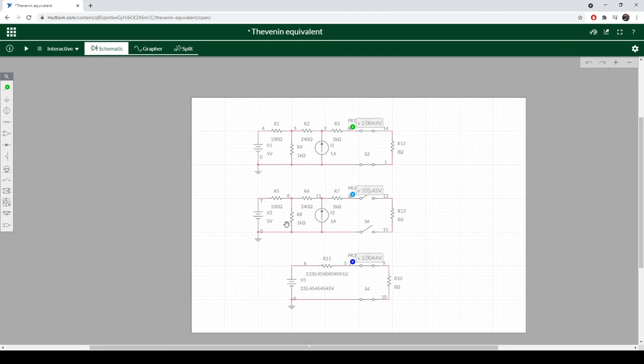Now you have to think, if you've got a circuit with thousands of components in it, this becomes an extremely powerful tool to know, so you can see how it affects different loads. It makes it easier for your simulation software to calculate this than a circuit with thousands of components, because it has to do that many more calculations. So that's what Thevenin is. It's basically just simplifying a complex circuit down to a series voltage resistance circuit.